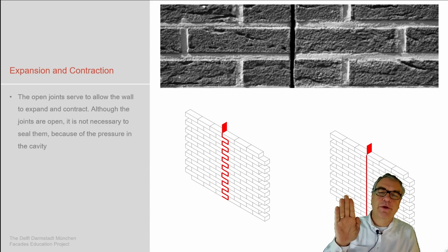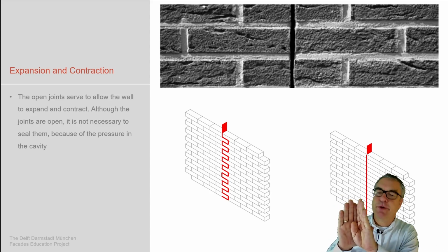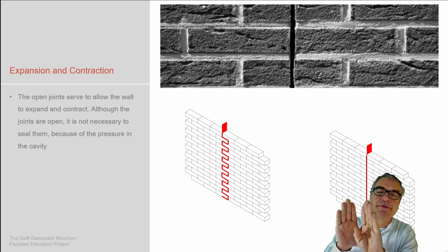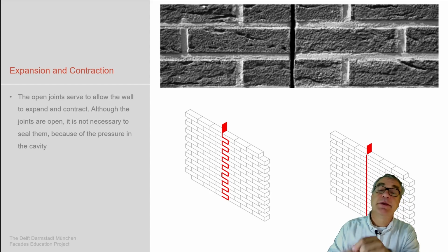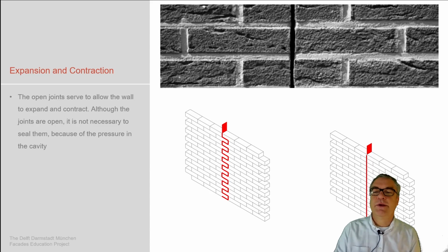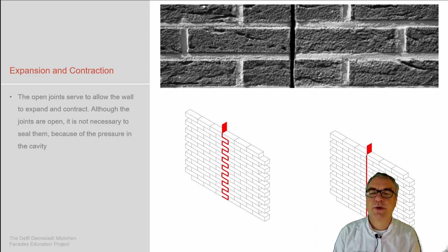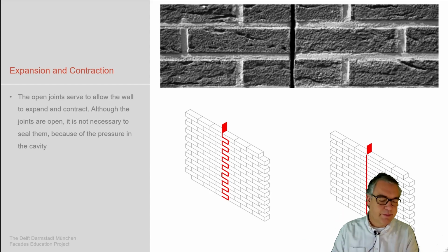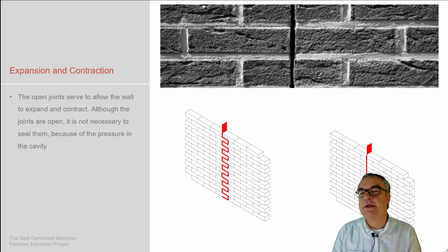in situations where we have one wall of outer layer of brick cladding and another wall of an outer layer, and they actually contact each other and they're exposed to sun in a different way, so that by thermal expansion, compressive forces are appearing within these systems. They need to be brought to a certain distance, and this distance needs to be sealed. And this sealing could be done either in a zigzag version or in a vertical version, which is obviously a lot simpler to handle. And then this is sealed in an elastic way, which allows then the movement of the bricks in these systems,